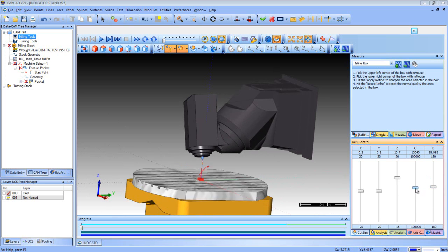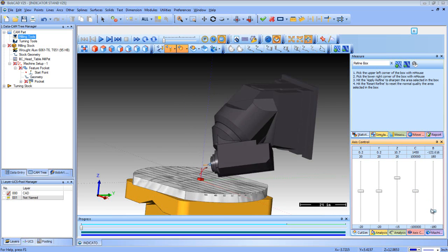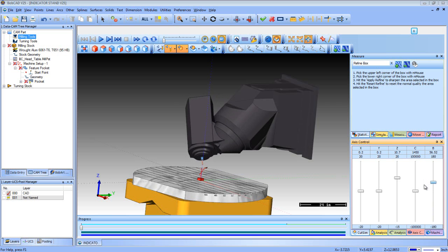There's also a C-axis, which is the table, and we'll configure that one as well. But we have to pull some numbers, just like any of the other machine configurations, off of this machine to know how far to set the travels and also figure out the position of the angle and the rotation point of the head. So we have to know a few things.